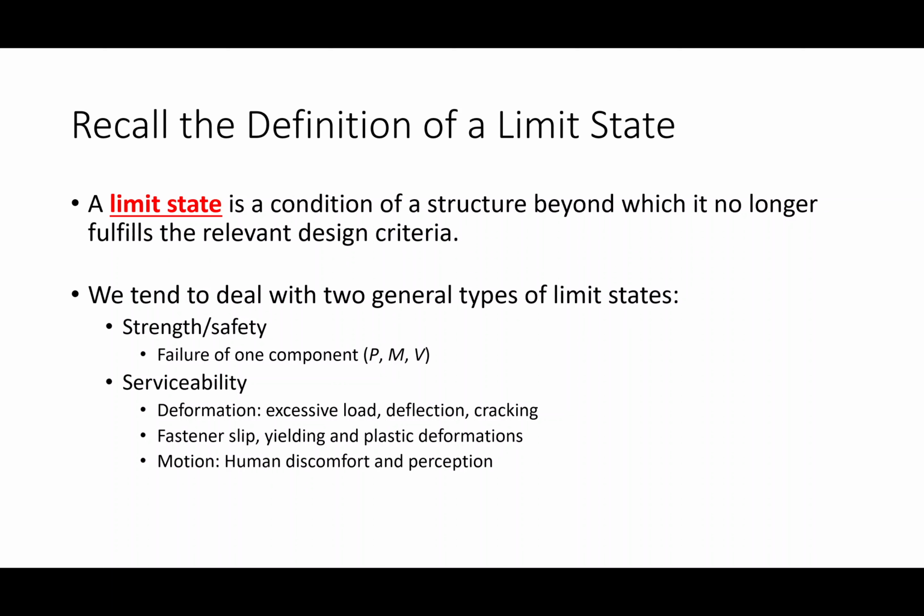So you can have certain connections or stiffener plates or things like that that can fail at stresses far lower than what you would expect under just a strength condition because of those cycles. So if you ever have a situation where a structure is subjected to a lot of cyclic loading, you might need to consider fatigue. I just mentioned that because I want to give you all a big picture idea of what's going on. All right.